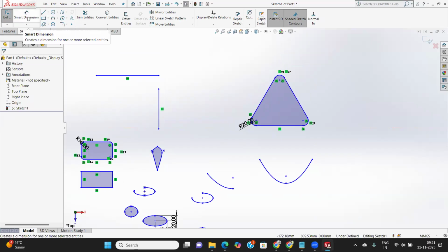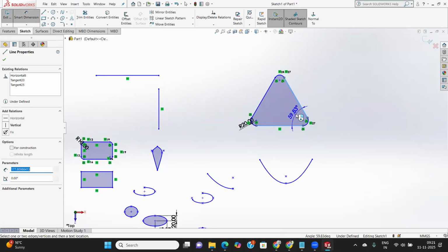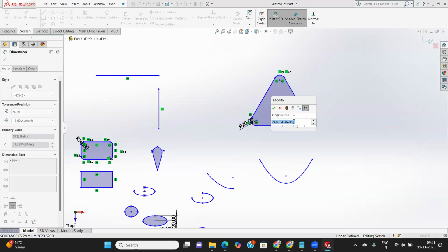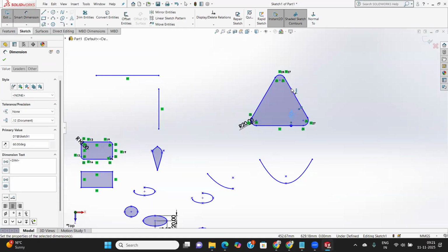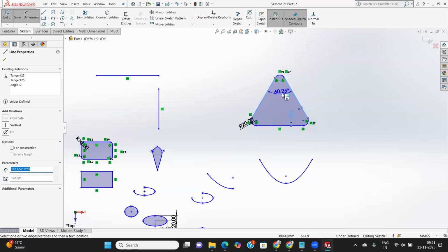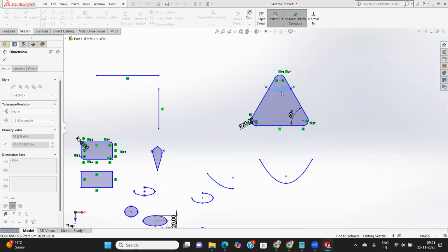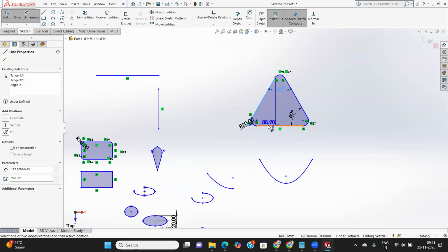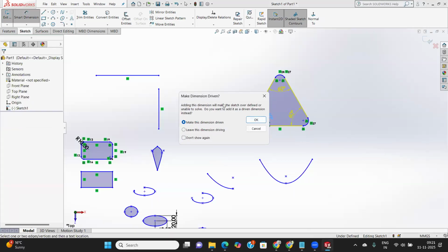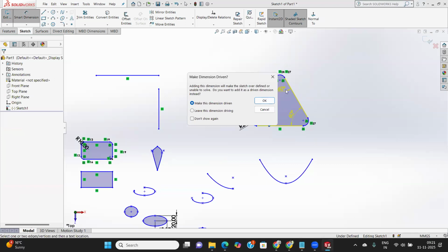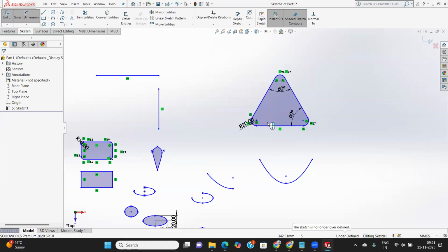I didn't get that. If you make an equilateral triangle perfectly, where all the dimensions are the same, then you can show the angle, right? If I click this and this, the angle will be shown. If your angle is not perfect, then write one angle, and after that each and every angle will be aligned. If two angles are applied, the third angle is automatically calculated. And if you click this portion and this portion and want to change it, this message will appear. Why? Because I defined these two angles, and after that the system already identified this angle as 60 degrees.